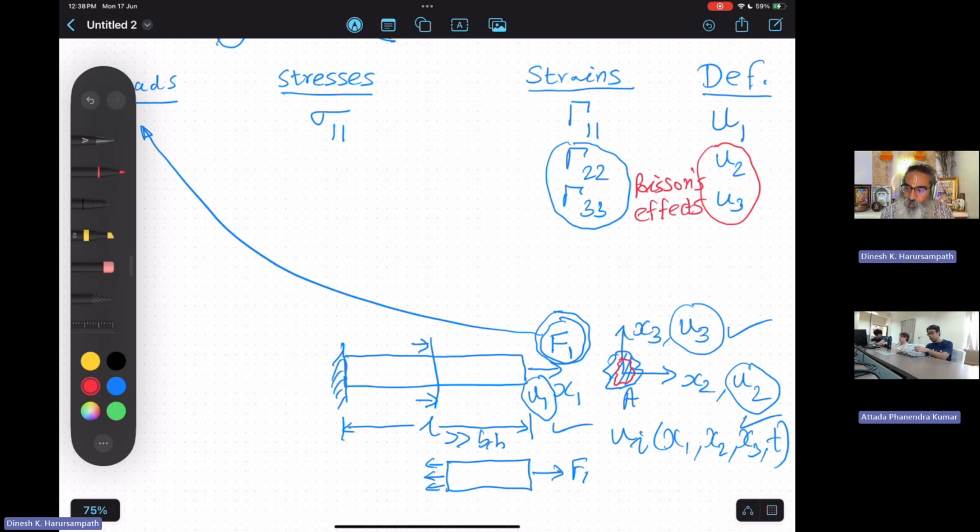They will be there because in most cases nu is not equal to 0, the Poisson's ratio in that particular direction that we are interested in, namely nu LT, and therefore you would have non-zero values for this. But there are some special cases where nu is 0, and therefore in those cases it will not be present. Whatever it is, that's not something that we are focusing on over here.